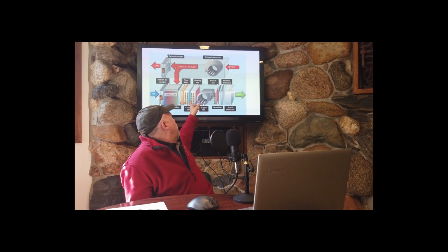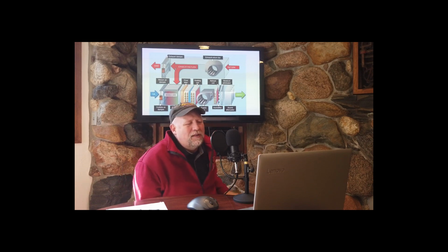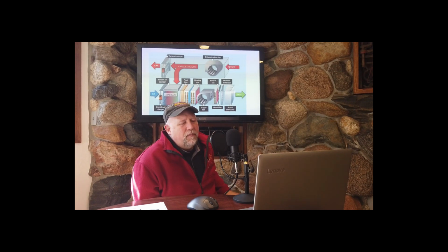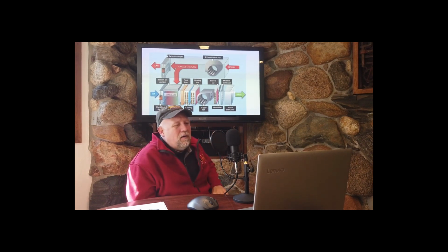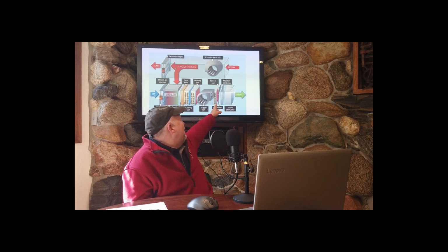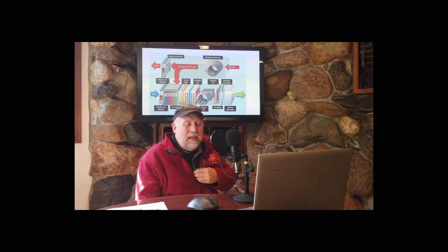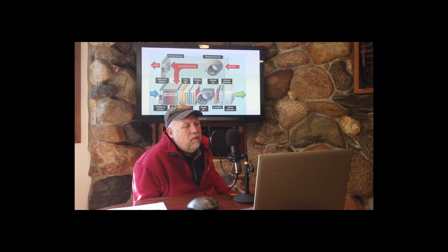Then we get into a cooling coil, a heating coil, right? A fan, and sometimes we will have a reheat coil. I don't discuss the reheat coil, but a reheat coil might be used if we had to really carefully control humidity. I might have to drop the temperature of this air down far below 55 degrees. Well, if we do that, that's going to dry that air out, but I might not want condensation within the space itself, so I'm going to reheat it here. I don't want you to include a reheat coil on your air handler for your final project. This particular diagram had one.